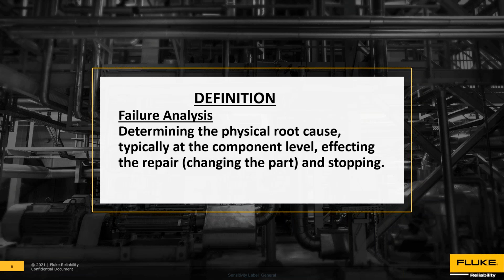So I want to start first with definitions, because I think root cause analysis is kind of a buzzword. It's a really important continuous improvement process, but people say, oh yeah, we did a root cause analysis, and all they did is they changed out a bearing. So a failure analysis is, okay, the bearing broke, I went out and changed the component, and we're good to go. That is really just a failure analysis, and that's probably more common than going through the full-blown RCA process.